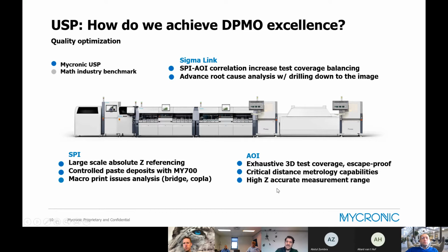And the same points for SPI and AOI. I will not go through all the points, but just to tell you that especially in the height referencing, I had this webinar the last time. Tuan recorded it as well, so we can send you the video if you are interested. How this Z referencing, so the height reference, why we are very strong on that and why it's so important, because for sure, if you are not perfectly measuring your height, then you cannot measure within a few microns.